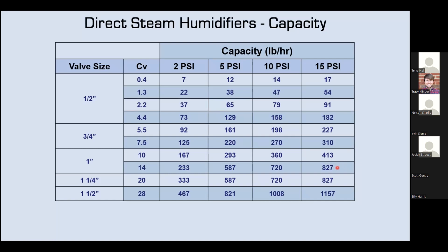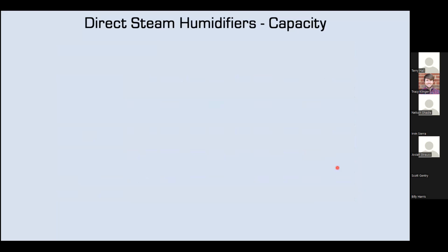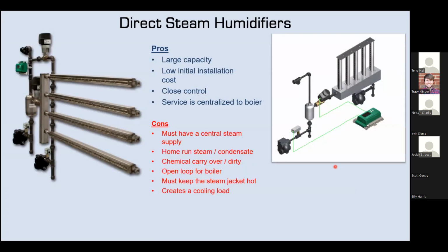And this can be an issue when no controller is used and you put a humidistat or a demand signal right on the actuator. So if I go back, right on this actuator, you put a 0 to 10 volt signal, and you get 100% demand, which isn't uncommon for a humidistat.